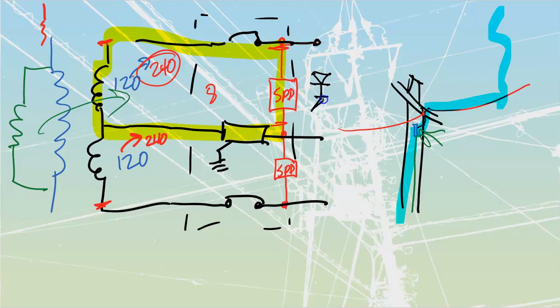Just draw that in over here. So one of these would always be blocking. These things are going to be back-to-back diodes that are going to be blocking until we hit a breakover. And at that point, then boom, they're going to shove current through them.